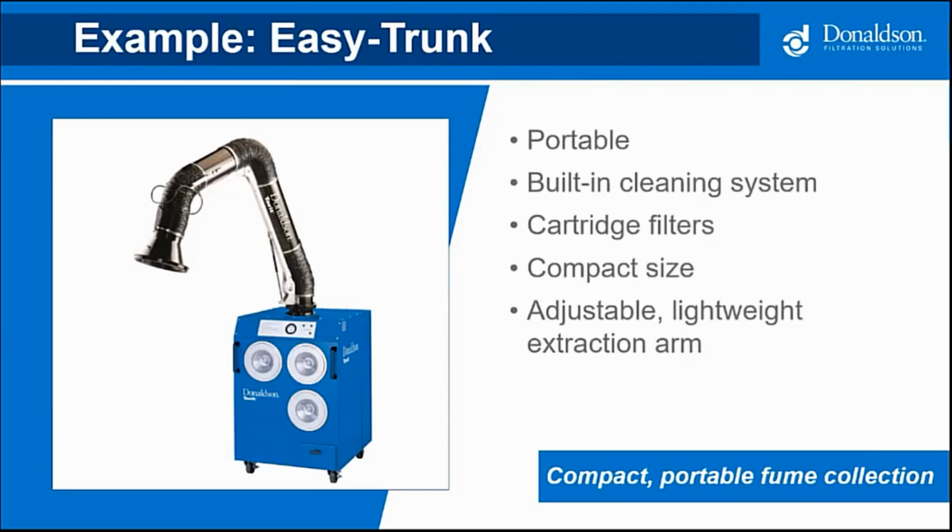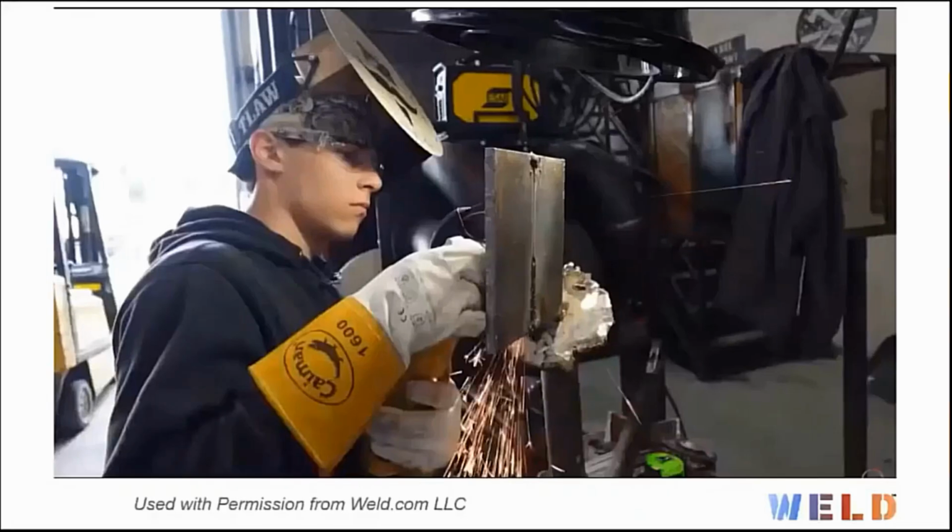Note the proximity of the hood in relation to the work, so that the thermal rise of the fume goes into the hood and not into the operator's breathing zone. So here we go.